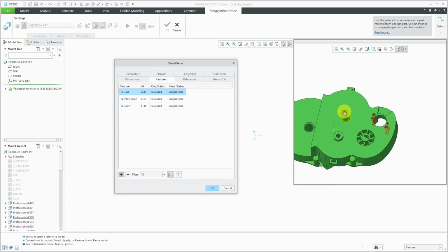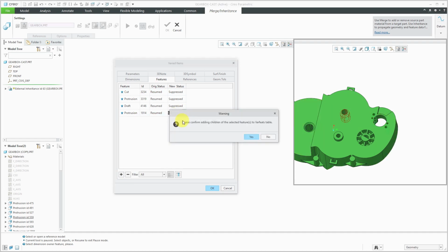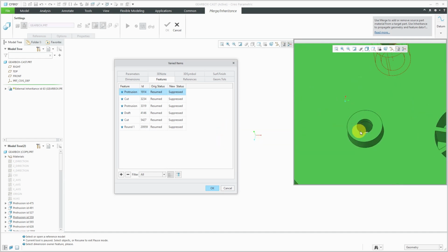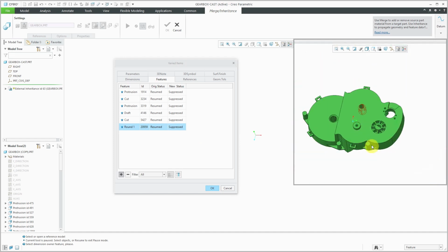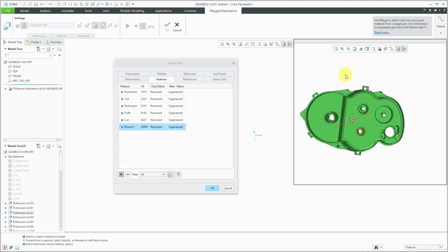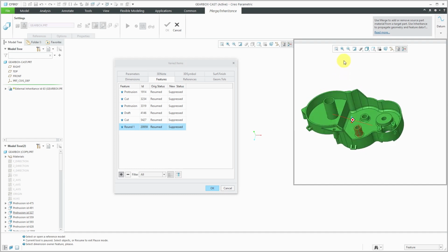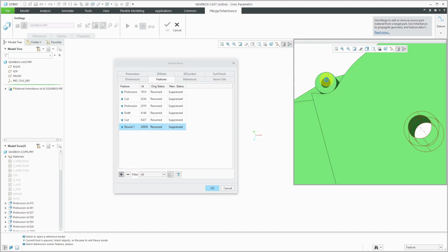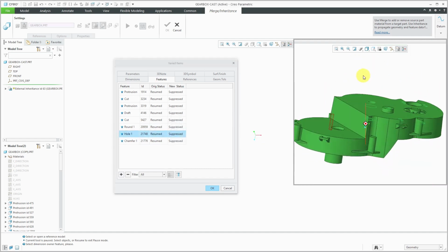Let's use the pick button. I'm just going to select a few other different features. Add the children, and let's see, let's grab one other one. Use the plus button, and then grab this one. Oh, looks like it was already grabbed. Let's find one more feature to throw in here. There we go. Let's use the plus button to grab this one and change it to suppressed and add any children that are necessary as well.